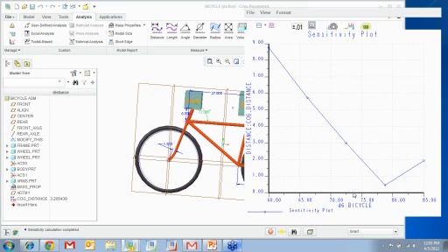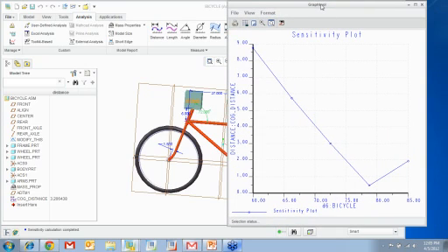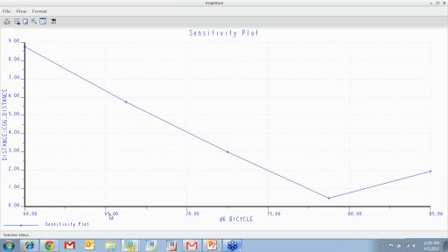So now it's going to throw you this little graph which tells you that as the distance changes from 60 to 85, you can see that the distance value is very low at around 78 or 79. Now, why is the center of gravity very important? The reason is that if I run an optimization, say I want to optimize this value such that the distance is almost 0, and if I choose a range from say 60 to 70, I would never get that value, because the value that we want is around this range.